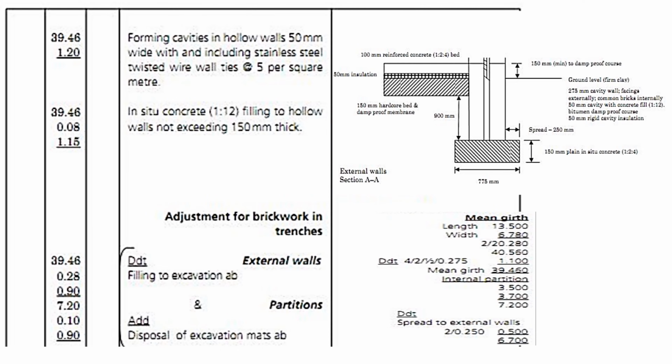For the internal wall, we shall take the total length of the wall, which is 3.5 plus 3.7. Remember in excavation, that's where we were deducting the spread. But for the walls, they have to meet the internal and the external. So the length of the wall shall be 7.2. Then we shall multiply by the width of the wall, for the internal is 100 millimeters, so it shall be 0.10. Then the depth up to the reduced level shall be 0.9. All these volumes of the two walls will be deducted from RFR and we add to cutaway. All right.